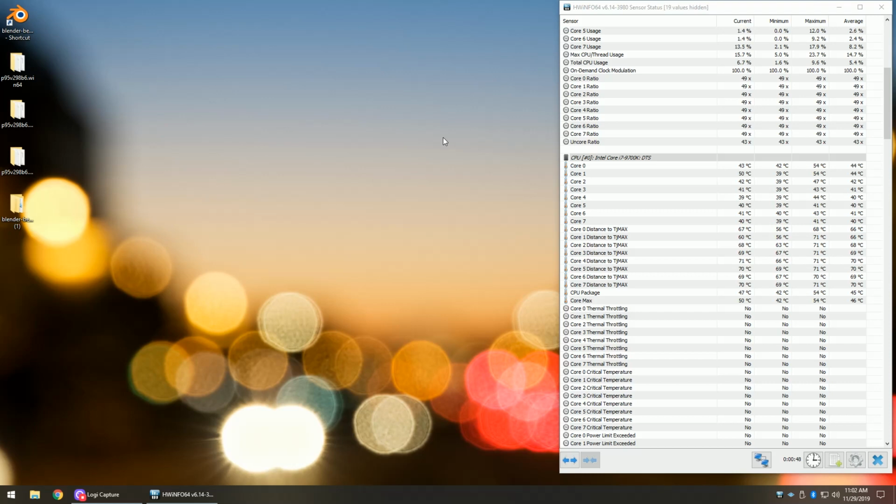However, I wanted to show you some bad results too. And this is an already verified overclock. It's going to stay within temperature on all the workloads that I stress test for. It's going to not overvolt, go past that 1.4 maximum V-core that I would want going into the processor, etc. However, what I see online is people asking if their overclock is okay. They're having some trouble. Maybe the temperature's going too high due to maybe the voltage going too high, or maybe their voltage is too low and they're seeing freezing, crashing, and rebooting of their computer.